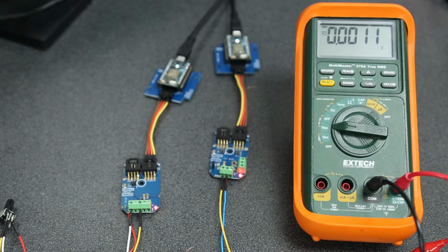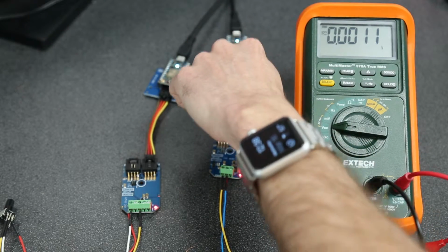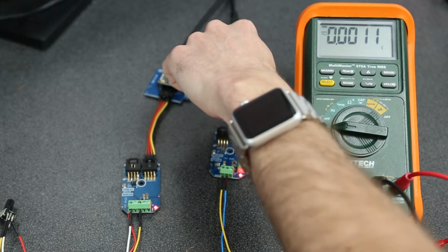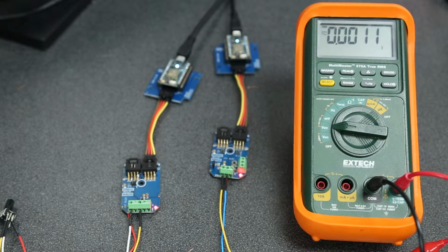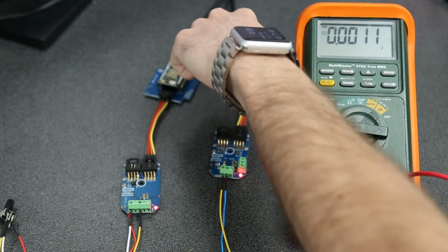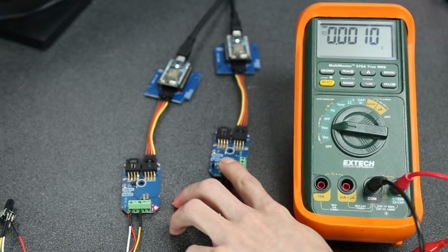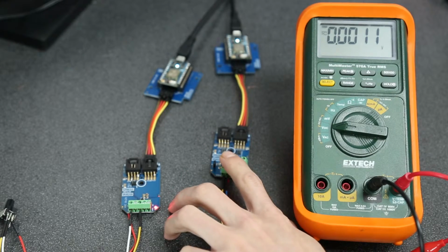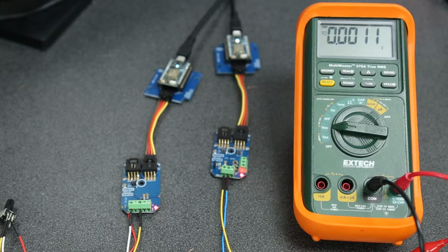And basically how we're powering the chip right now is we have a USB cable coming into our Particle Photon module, and then that 5 volt supply comes out of the Photon module through its VIN pin, and then that 5 volt supply comes through the I2C cable to the mini module. And what happens is whenever you come in through that USB connection on the Photon and then you tap off that VIN pin, you're actually going to get a little bit of voltage drop. It's somewhere around 4.6. So the maximum voltage output we're ever going to get out of this DAC is about 4.6 or so due to that. If you were actually supplying this mini module with a real 5 volt DC signal, you would of course have a 5 volt DC output.